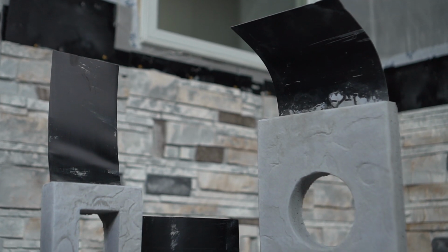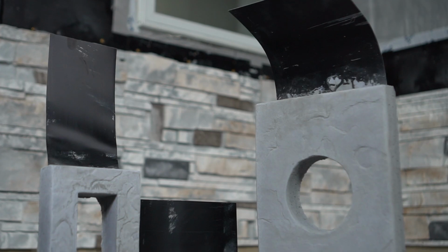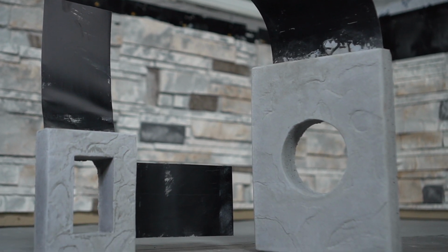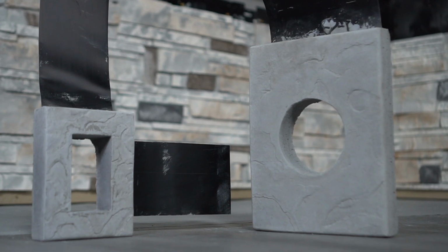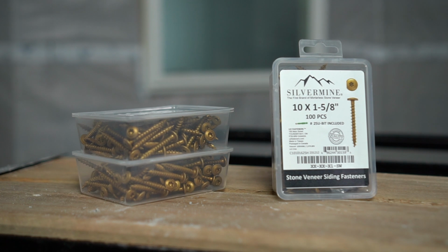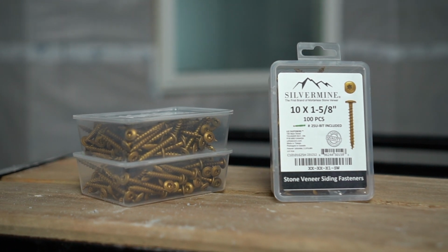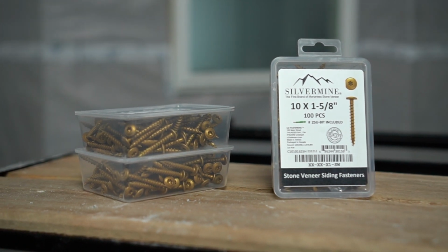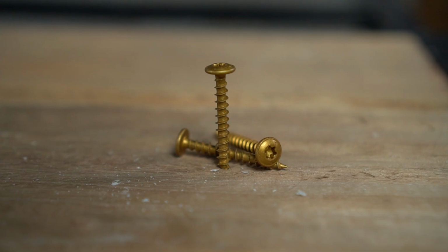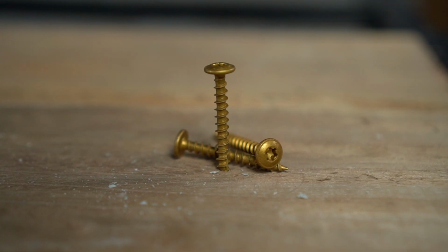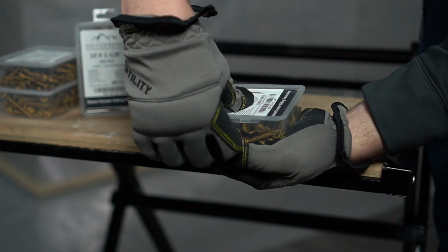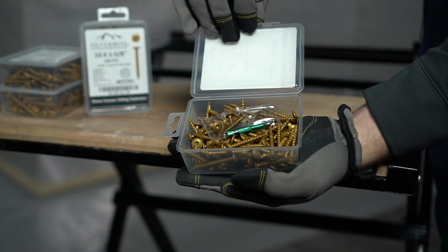Silvermine Stone offers additional accessories, including light boxes and receptacle boxes that allow you to provide finishing details around electrical outlets and light fixtures. One smaller but very important piece of the Silvermine Stone system is the Silvermine Stone screw, which comes in a 1 5/8" length, allowing for the proper wall and stud penetration, and features a pan head, which is designed to seat into the metal flashing to provide ample holding power and water protection. Screws are available for both wood and masonry substrates.